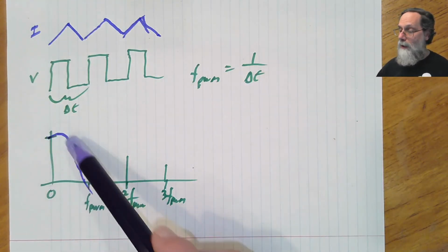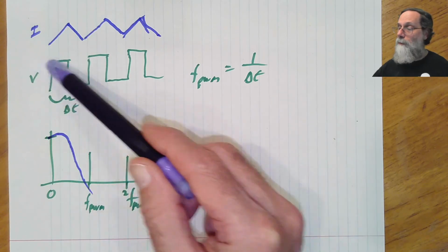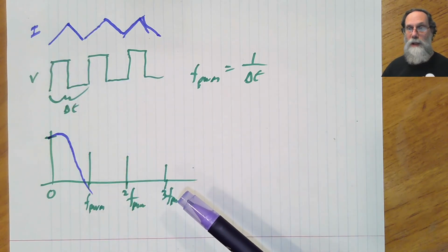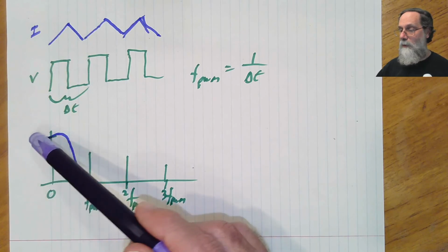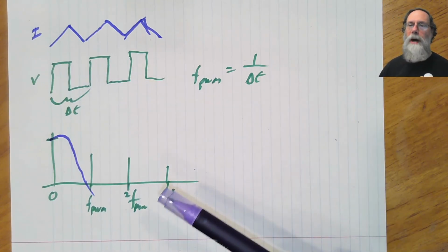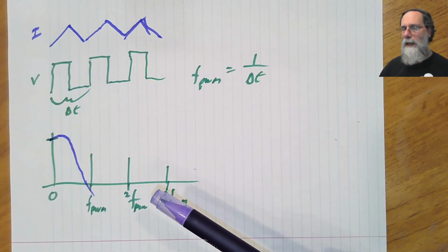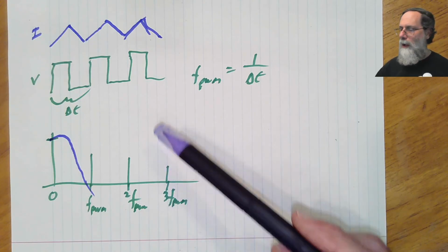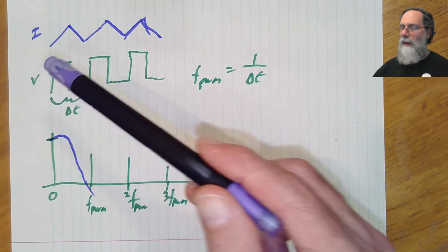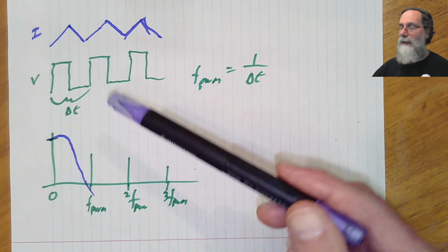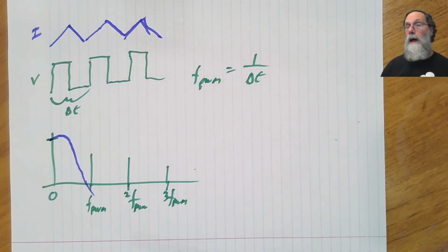But we'll also put in a filter so that even the voltage doesn't change much. So we'll have the pulse width modulation signal coming out of the Class D amplifier. We'll run it through a filter that smooths it out quite a bit, and then the fact that there's an inductive load smooths that out even more. And so we'll have very little fluctuation, very little high energy at the high frequencies, and just the audio signal that we're trying to get to the loudspeaker going through.